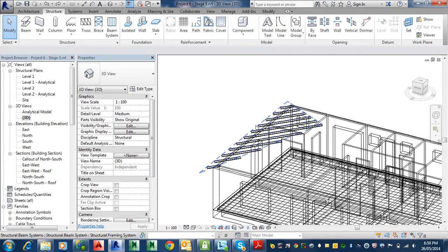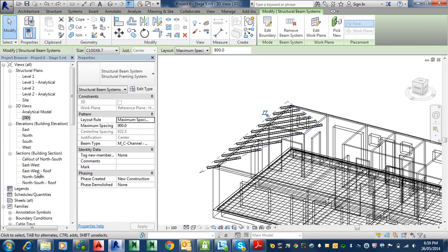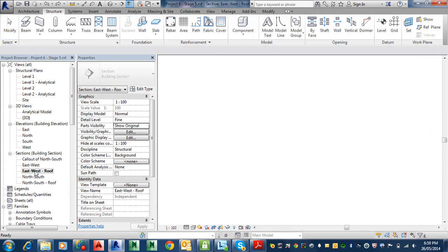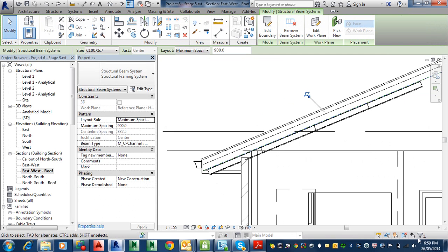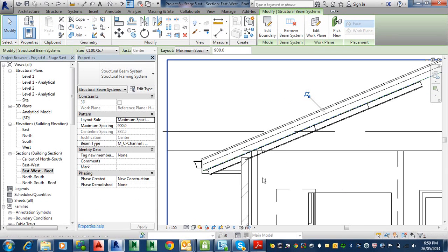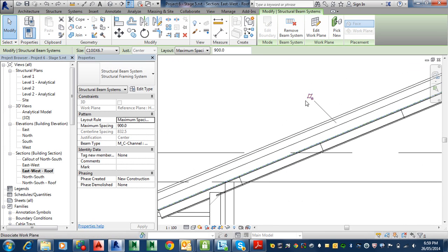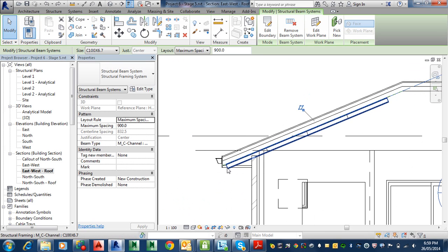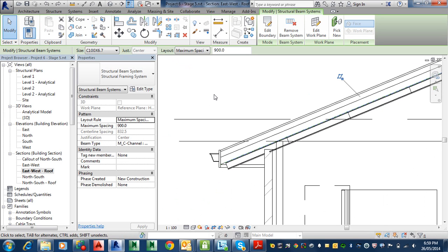See if I can select it from here like that. And now I wonder if I can go to the east-west. It still says it's got one selected in my filter, so it means I've got it. And it looks like it's locked to that plane, by the look of it. So I should be able to hit the move command, which is basically all that paragraph on step 15.